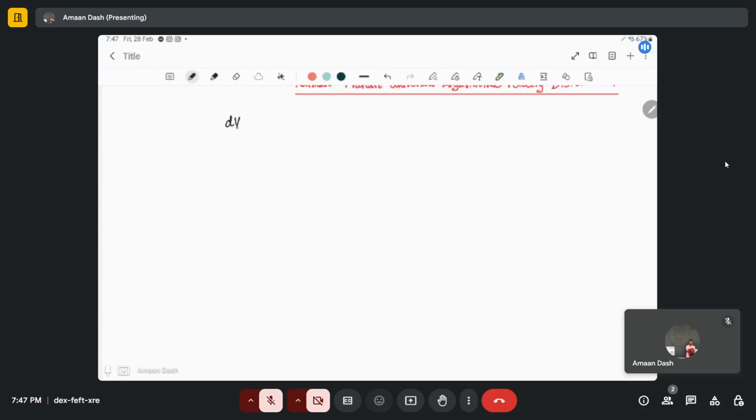Let me write so that you can get a feel of what it is. Let's see, dVx by dy is equal to V star by y, times b0 plus b1 by log of Reynolds number, and we have y V star by nu to the power of beta 1 by ln of Reynolds number.